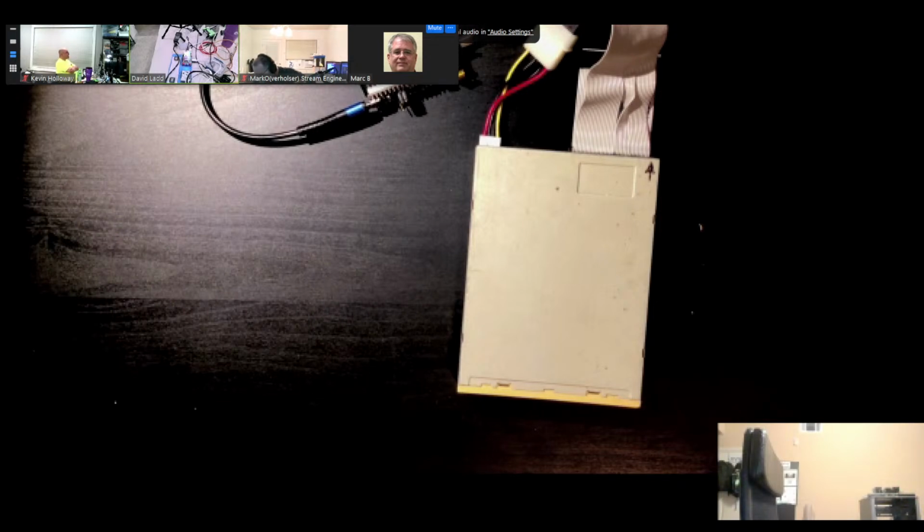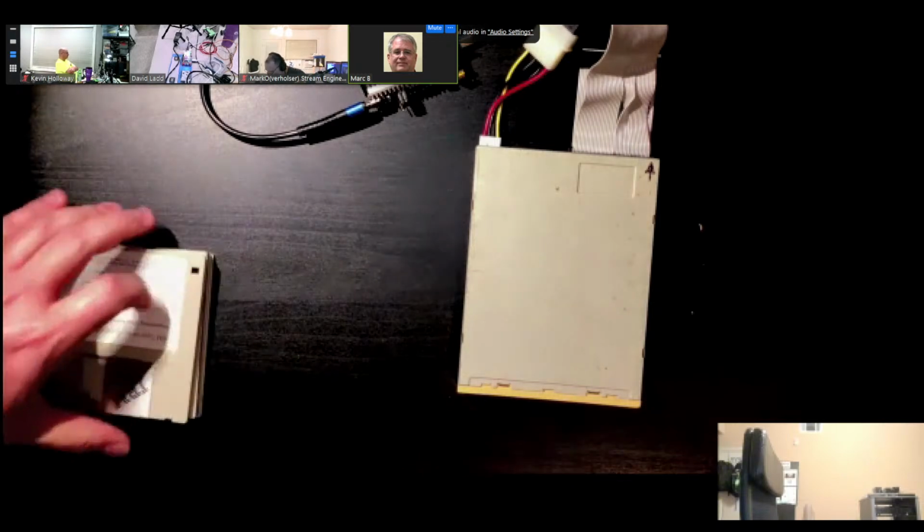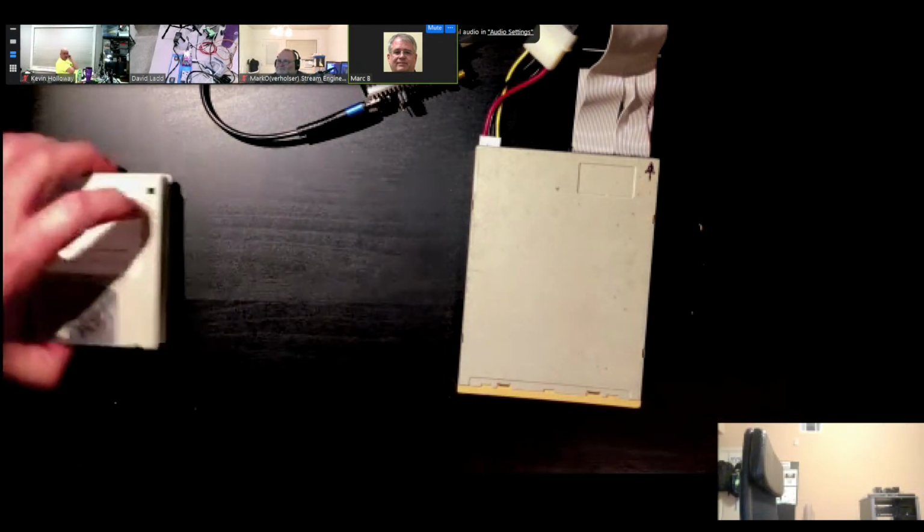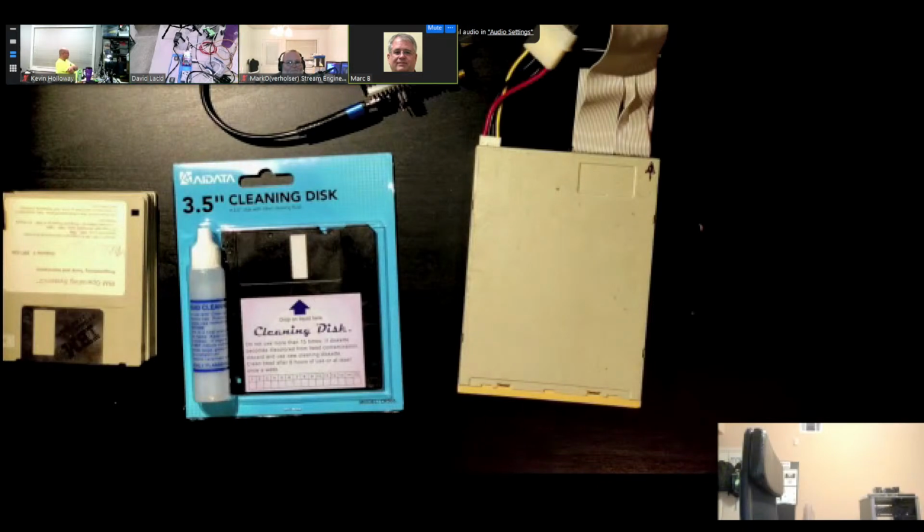Except if you're dealing with the Macintosh floppy drives, pin 1 is actually a separate pin, and that controls the eject motor. Oh, don't forget the external Tandy 1000 floppies. Yeah, I'm not experienced with those. Well, they brought the power through the data cable too. I didn't realize I had a couple of the Macintosh floppy drives until I plugged them in, and the drive auto-ejected the floppy disk.